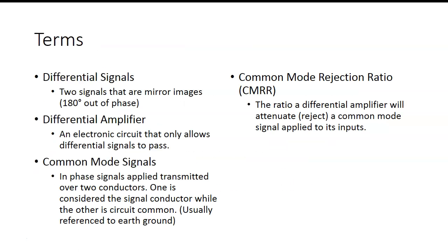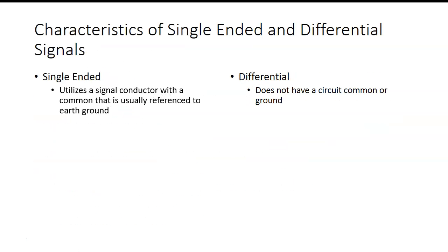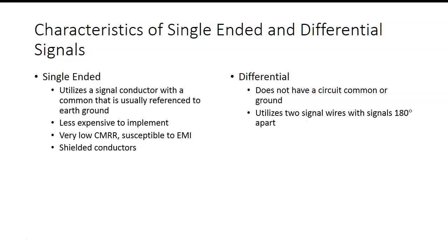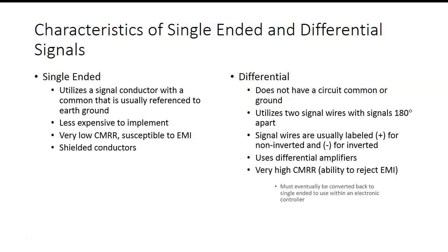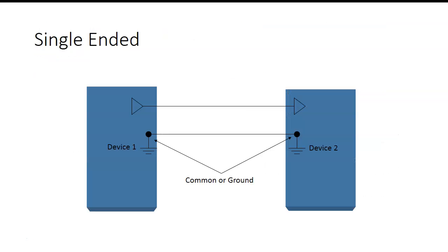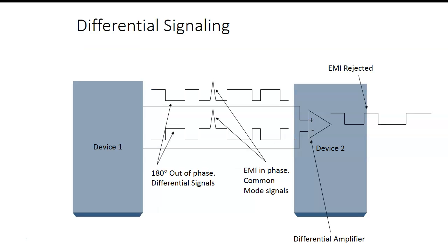Sensor output, we looked at that. Current loops, we looked at the single-ended and differential. All the sensors we're going to be dealing with in this class are single-ended. We talked about how single-ended is very simple. Then we look at differential, where we have new electronics.